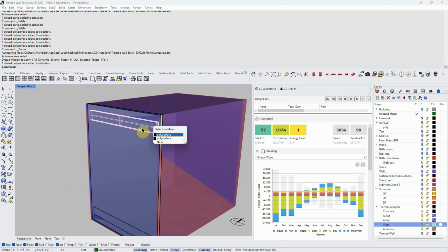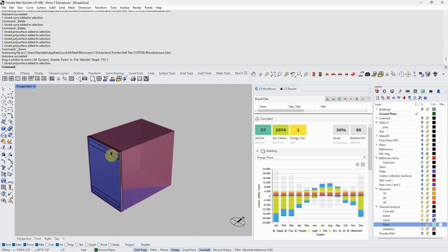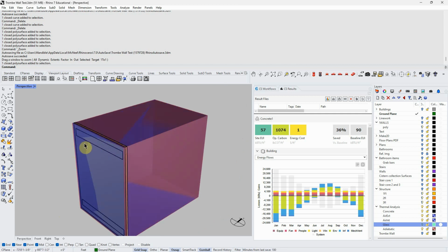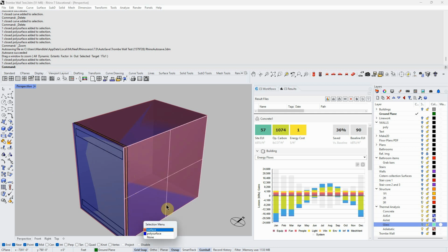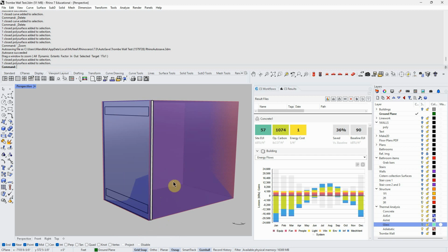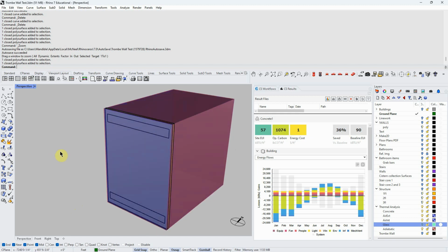in here, and then I turned these into air zones because the idea is supposed to be that the air in here heats up in this airspace because of the glass, and there's this little hot box here, so that it gets pretty hot in there, and then hot air goes through this zone at the top, just this hole, and then that hot air creates a displacement in here that needs to be filled as it moves into this space, and so that pulls air in from the bottom, which is a little bit colder down here, the bottom of the floor, and you create just what's called a thermosiphon, and it just moves around in a circle and passively moves the heat from this volume into the space,